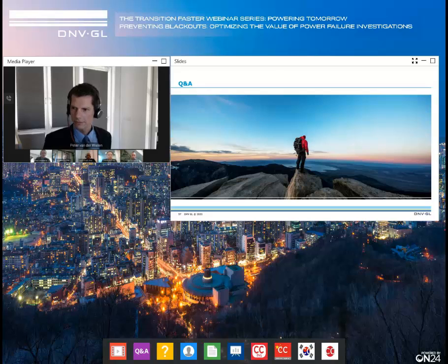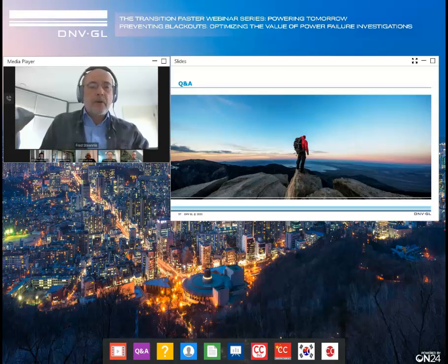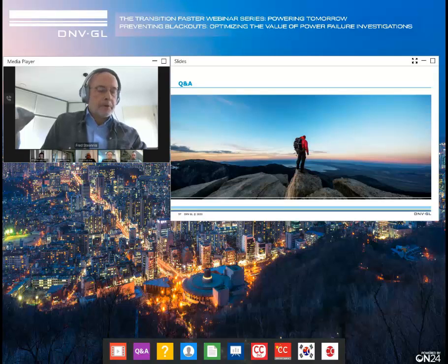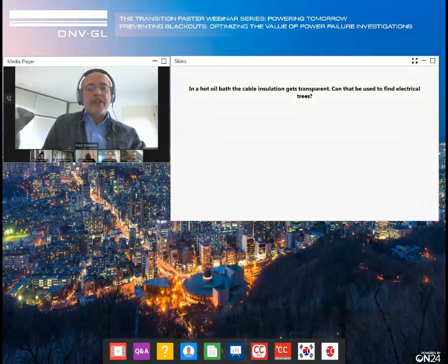Yes, Peter, thank you. Nice question indeed. Well, the hot oil bath is certainly a possibility, but realize that in a hot oil bath you see an insulation sample with a thickness of about 10 centimeters, and electrical trees can be quite small. So you can get an indication, but making slices around the breakdown channel is often the better way to really see electrical trees and get confirmed. So the better way is make slices, and the hot oil bath can be used, but is a bit uncertain way to see them. Okay, clear. Thank you very much, Fred.